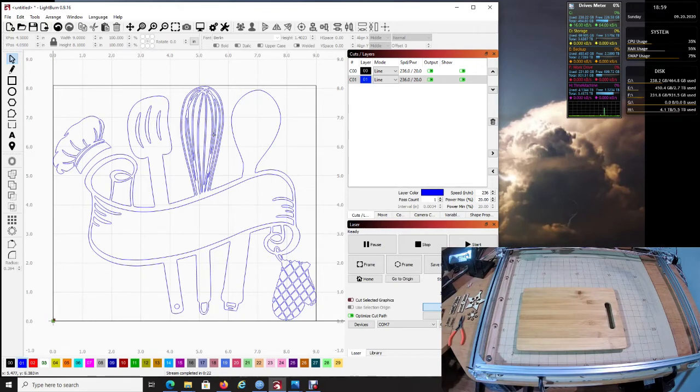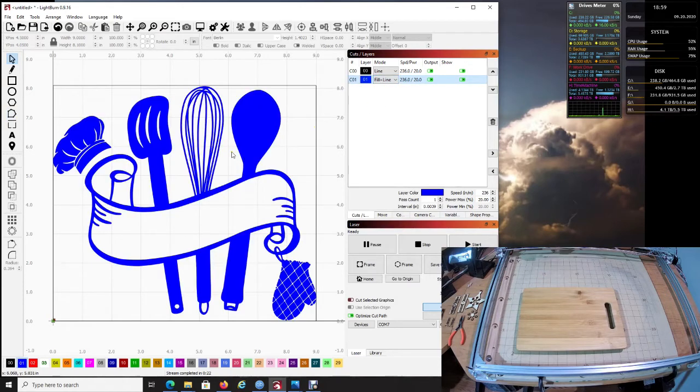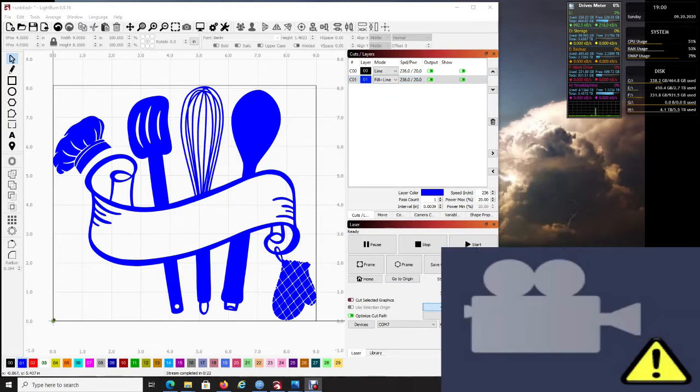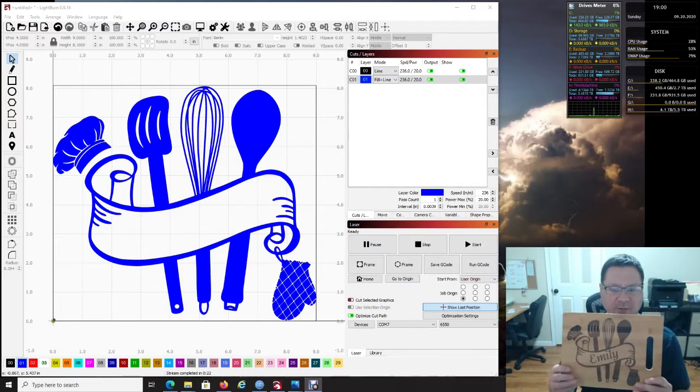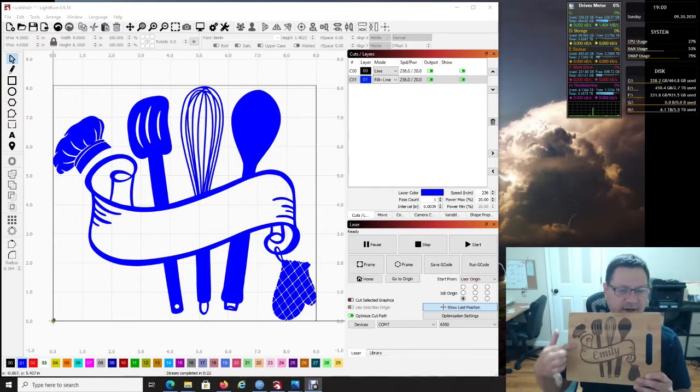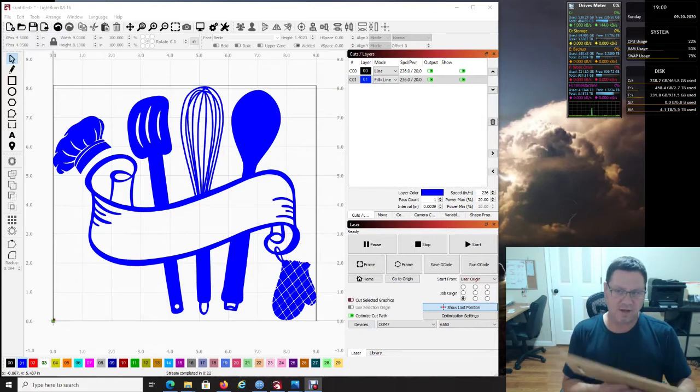So now we don't want it like this. We're going to want it fill and line because we want it filled in like this. But the box, of course, we're just going to leave as a line. So for the SVG, we're going to change this to fill and line. We'll change all the powers in a minute, but that's the look that I'm going for. If you see my camera here, the one that I already burnt is exactly the look that I'm going for, and it's going to burn right on the lines that I specified, and it's on its own separate layer.